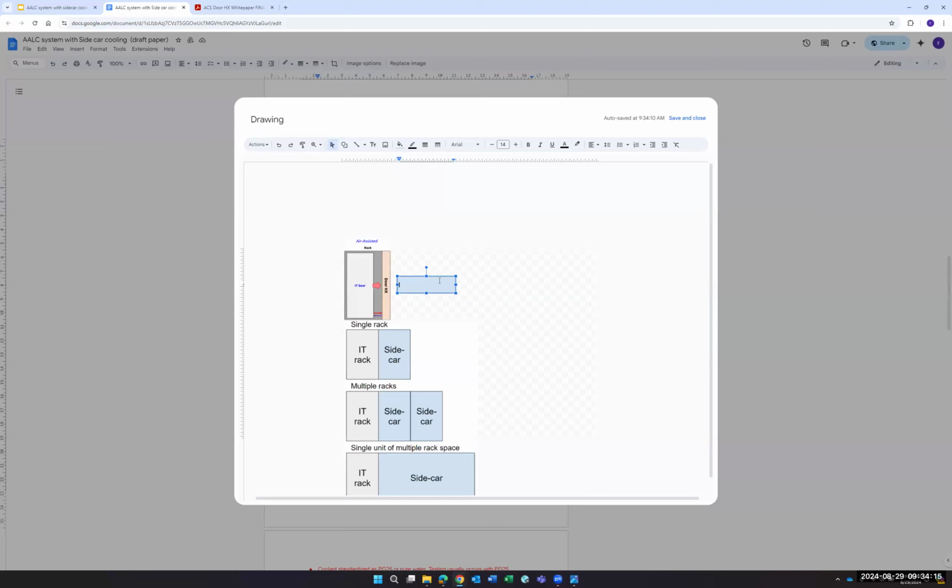I think then I would definitely need Juan's help in terms of approach, because for a certain approach, usually the powers are within plus or minus 5K-ish. It depends upon the airflow for sure, but usually they are very close. But we could find some typical numbers on this for approach temperatures and then the resulting cooling capacity based on those approach temperatures. And that's going to have some practical upper limit for what a rear door heat exchanger can do.